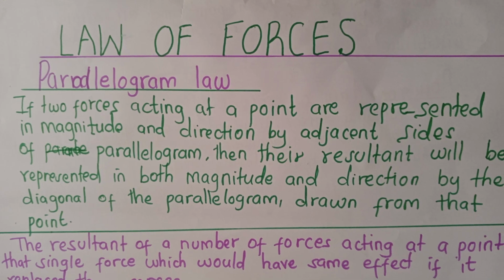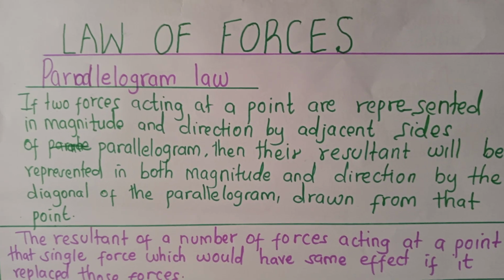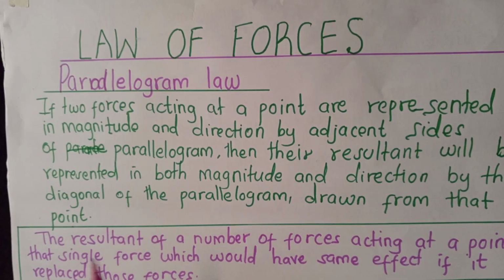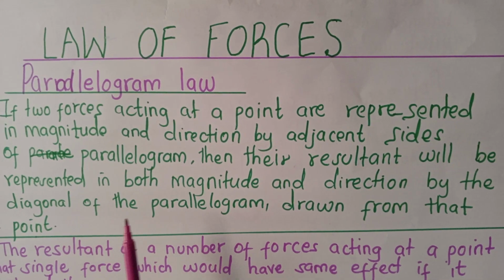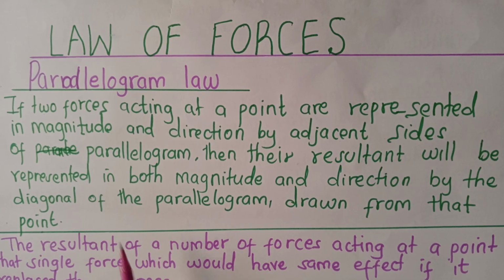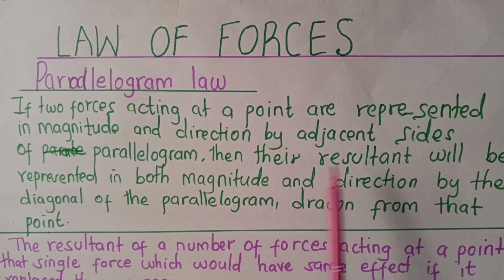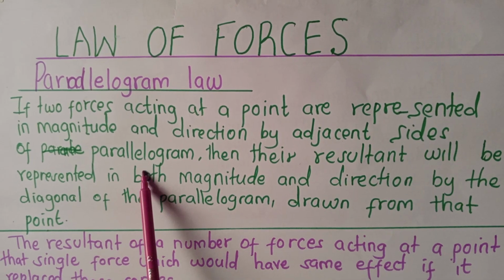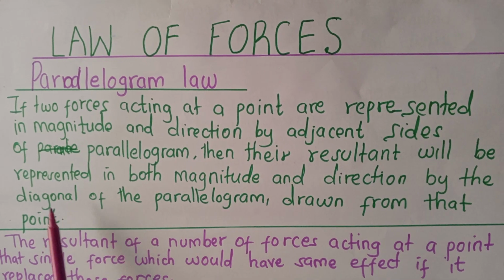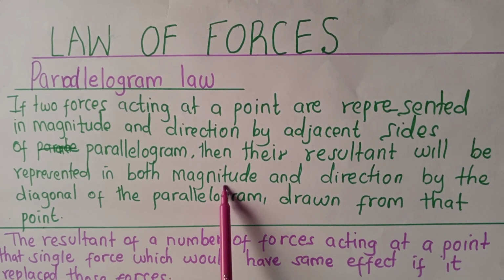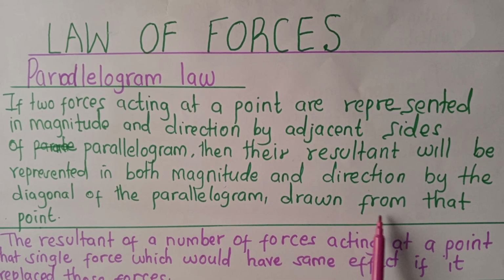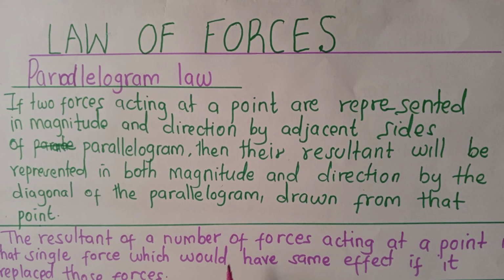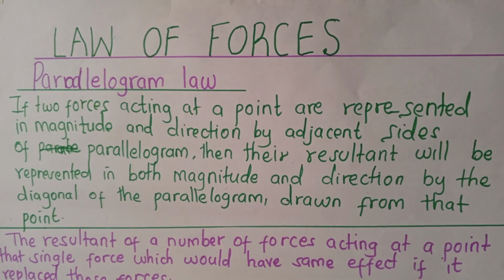The law of forces: parallelogram law. The parallelogram law states that if two forces acting at a point are represented in magnitude and direction by adjacent sides of a parallelogram, then their resultant will be represented in both magnitude and direction by a diagonal of the parallelogram drawn from that point. I'm going to illustrate it.